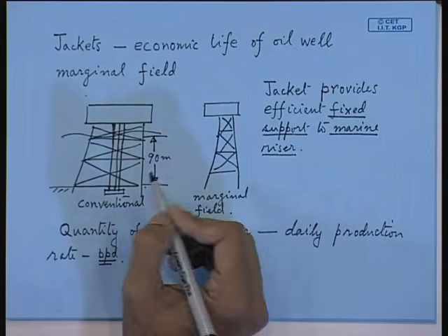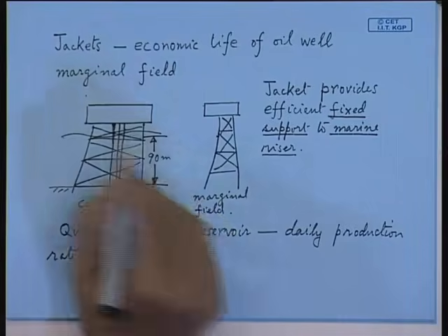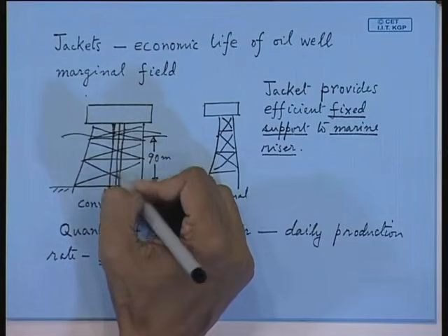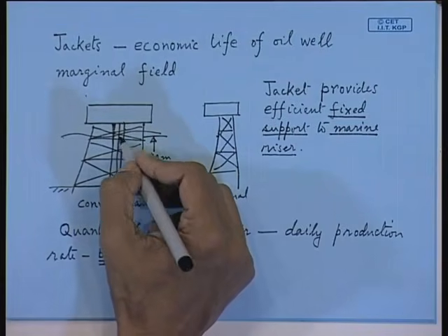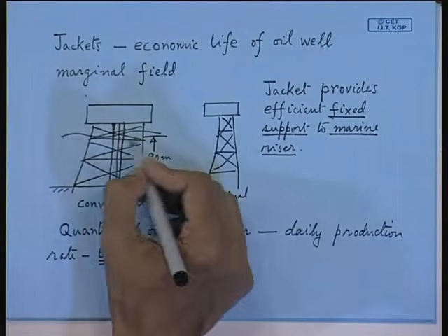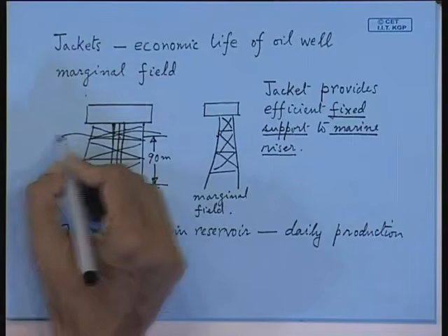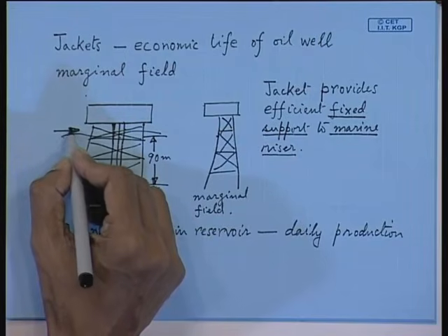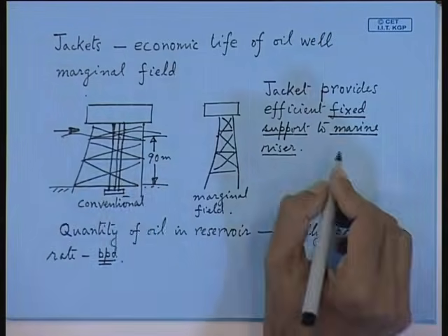So, that is one method. So, you can do your finite element calculations with a beam supported at these support points. Wave load is coming in the horizontal direction. So, this I told you is an important study. These are called riser mechanics.